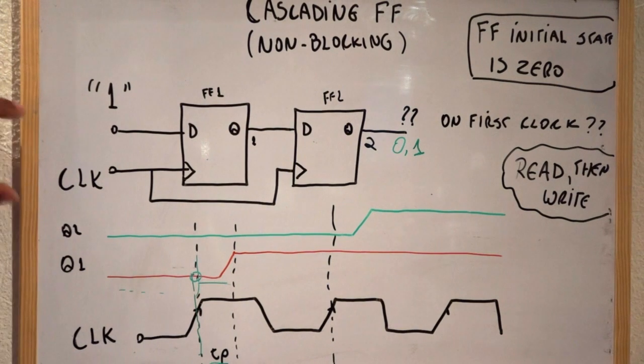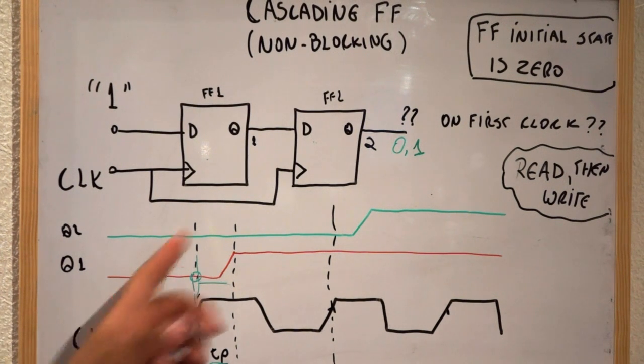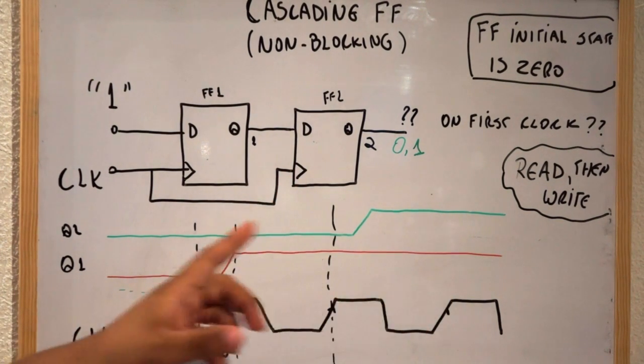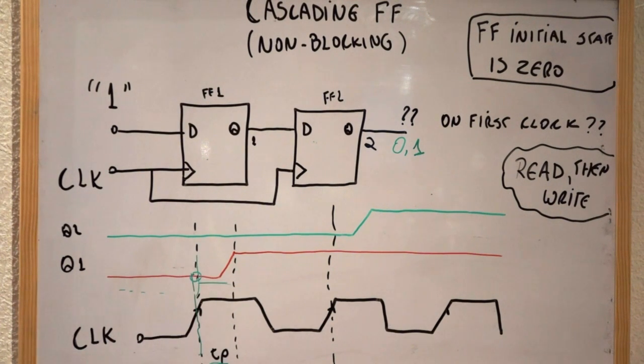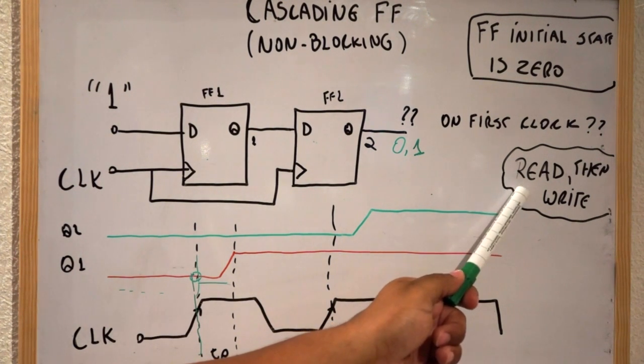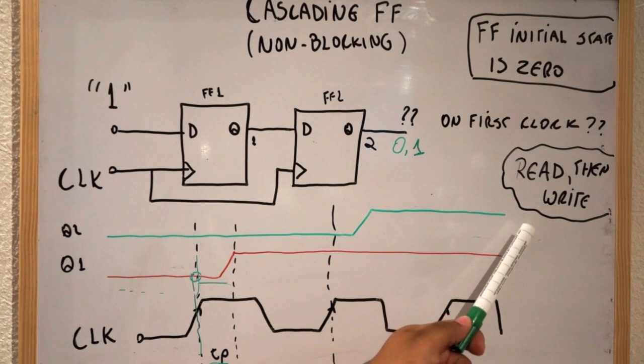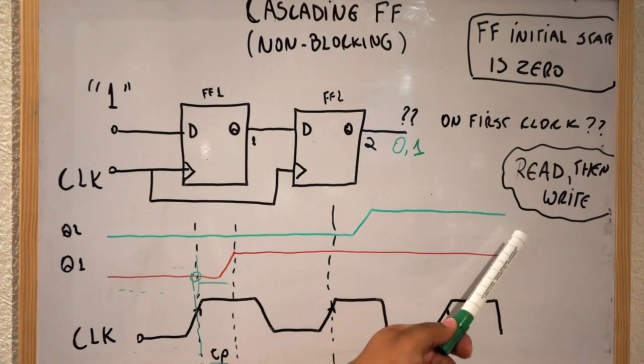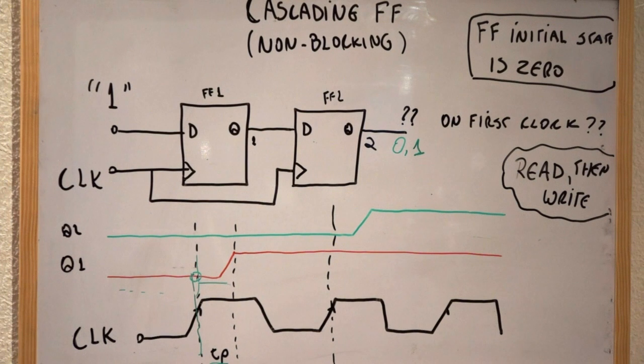So what you have here is a kind of delay circuit. The input will be delayed by one clock edge. If you have 10 flip-flops, you're going to have a delay of 10, and that's it. The whole point was to explain that there is a physical limit on the device: the flip-flop will read and then write at different times. It is not going to read and write at exactly the same time. There is always a propagation delay, and this is what we're going to see now.